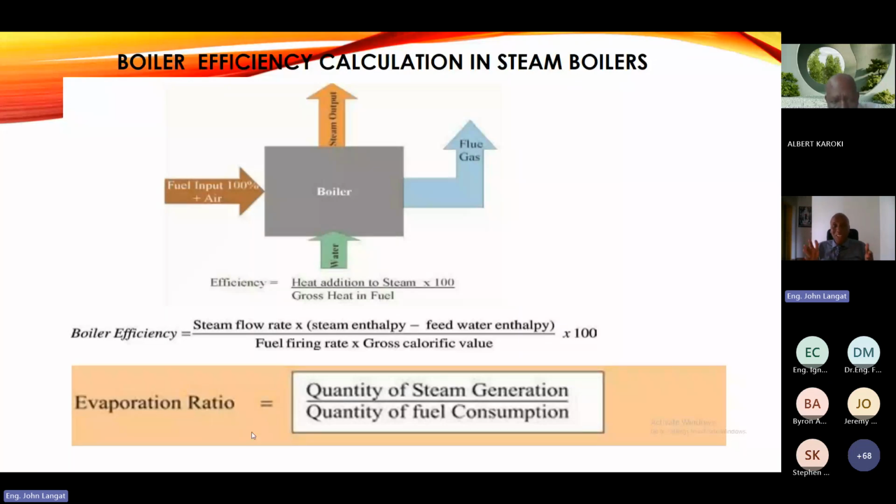So in essence, you need to dedicate at least 2 days, even if it means giving maybe 3 hours in a day to check that. Then you go do any other audit or any other measurements. Then tomorrow you come back again to the boiler house, then you check also. So don't just go there for 2 hours. As Engineer Felix mentioned, you do power logging for the FD fan and the ID fan. Then you've already audited the boiler house. The boiler house is a lot. We've not even mentioned the steam system, not yet.